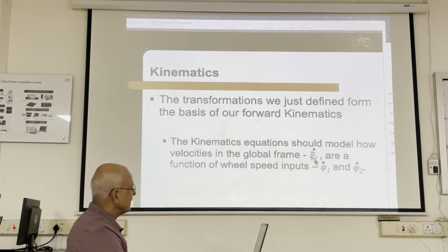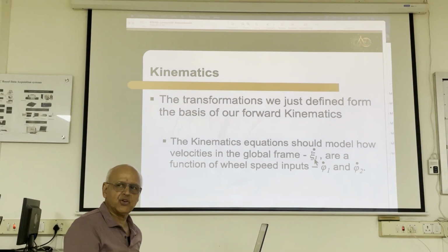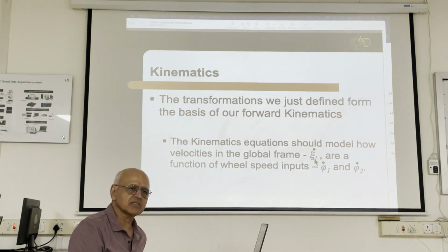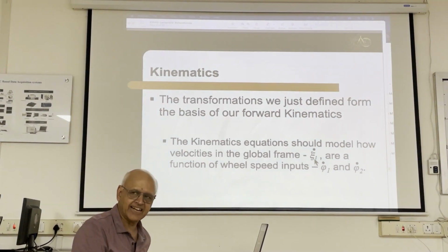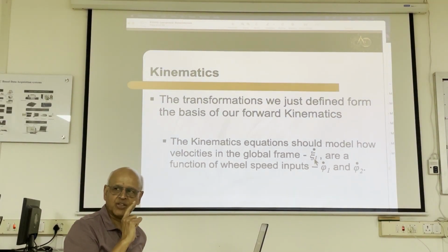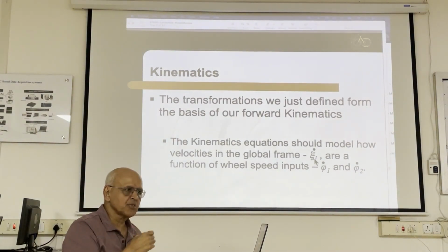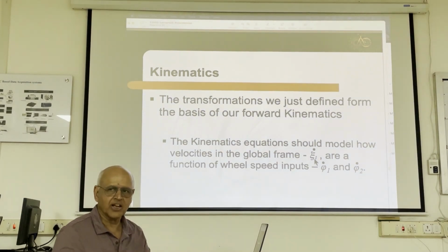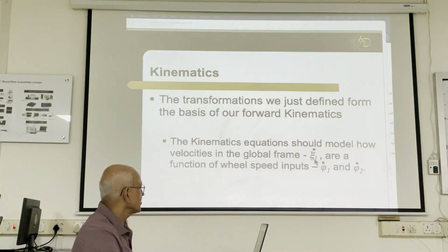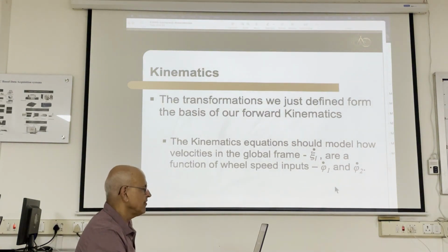So we have psi dot, right? And I said that if you integrate it, you get the position. And I also said that computers most of the time numerically integrate it. But we are about to integrate and get a result, because for the differentially steered vehicle, with certain assumptions, it is possible to get what we call a closed form result. So that's what we're going to do. And we just introduced two new variables.